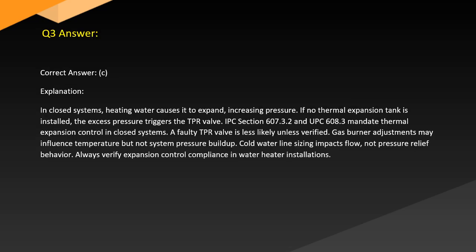Answer. Correct answer C. Explanation. In closed systems, heating water causes it to expand, increasing pressure. If no thermal expansion tank is installed, the excess pressure triggers the TPR valve. IPC Section 607.3.2 and IPC 608.3 mandate thermal expansion control in closed systems.